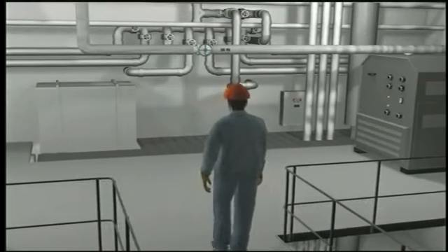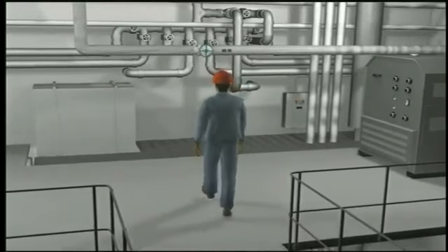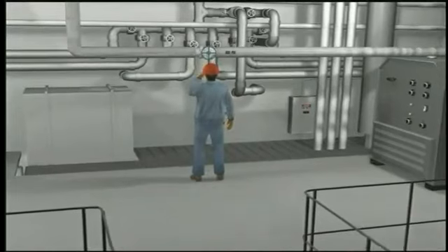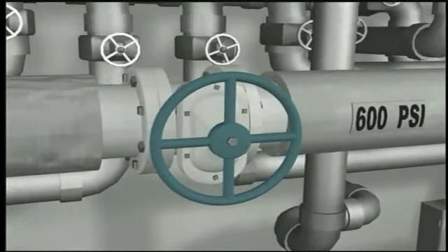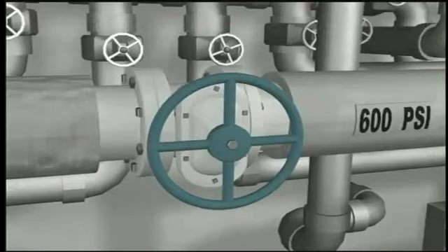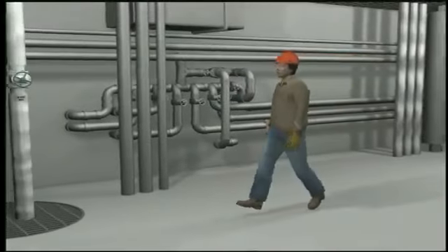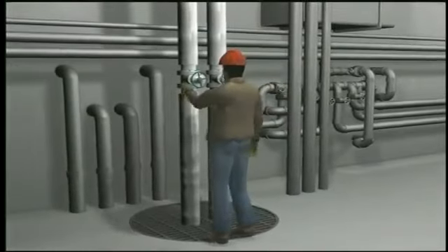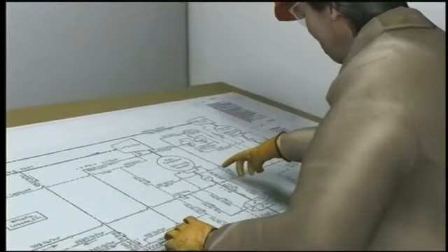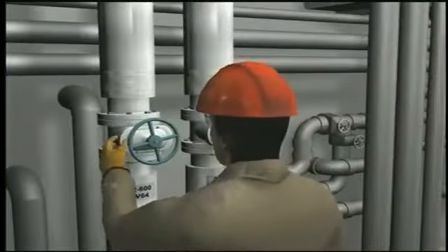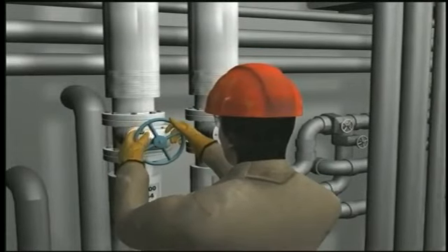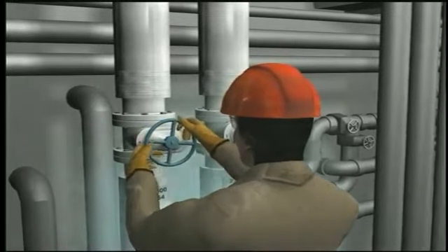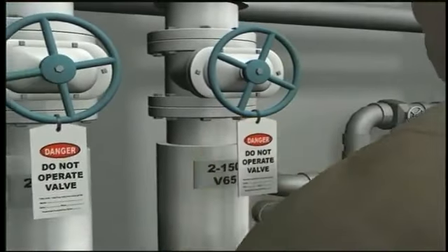A shipyard worker was preparing to replace a high-pressure steam valve that was faulty and leaking in an engine room. The valve was part of a 600 psi steam system on a vessel. Other shipyard personnel had previously located all the valves and drains and isolated the steam system according to the ship's as-built drawings. All the drains indicated on the as-built drawings of the ship were opened and depressurized. The drains were then marked with tags.